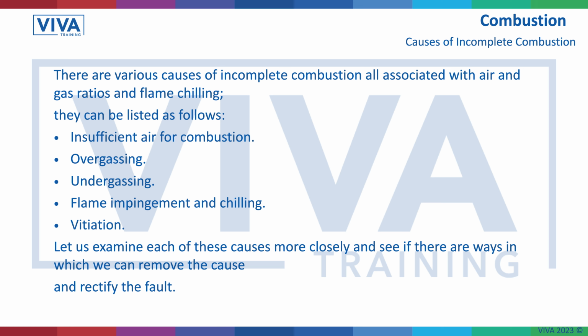It could be the flames are touching each other. It's what's called flame impingement, which causes chilling. The flame should be hot, but if they're touching, you get flame impingement and flame chilling, which can affect it.